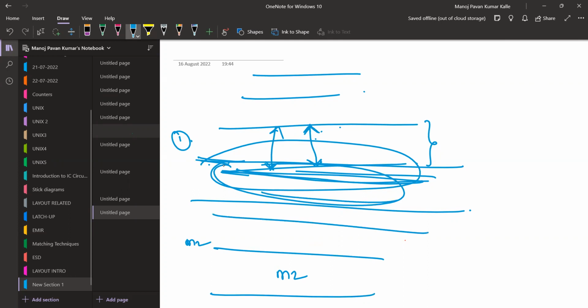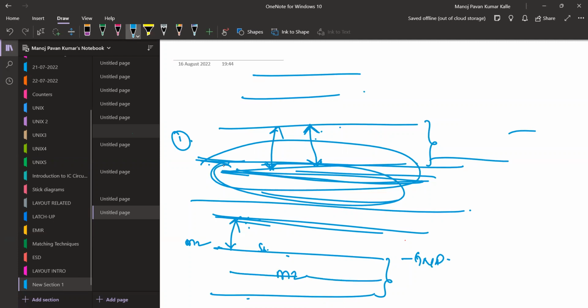And here we have some other signals. It doesn't matter what metal or whatever signal we have routed here. Whatever impact the signal shows falls completely on this shielding metal only, and these two shielding metals are connected to ground. So only the shielding metal will see the total impact from the other noisy signals. The main critical signal will not see any impact from the noisy signals because it is shielded, right? It is covered with the ground signals. You understood, right? Yes, sir.